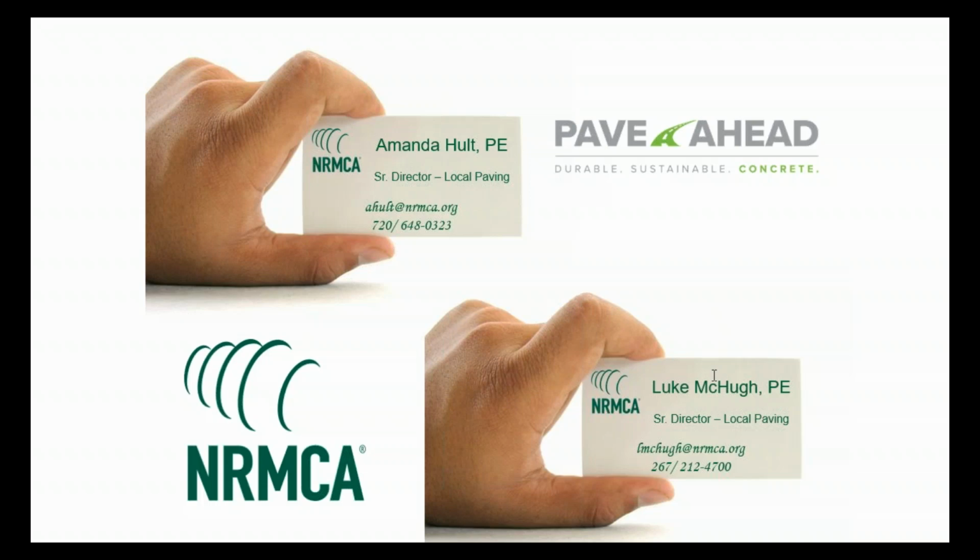There were four scenarios where sealing was always recommended, let me see if I can pull that up real quick. That's if you're in an area where you've got potential chemicals that could contaminate the soils, or fuel. If there's an area that's going to be a ponding zone around stormwater drainage inlets, a lot of times those will settle somewhat, and so they'll accumulate water around them. Corrosion is another one.